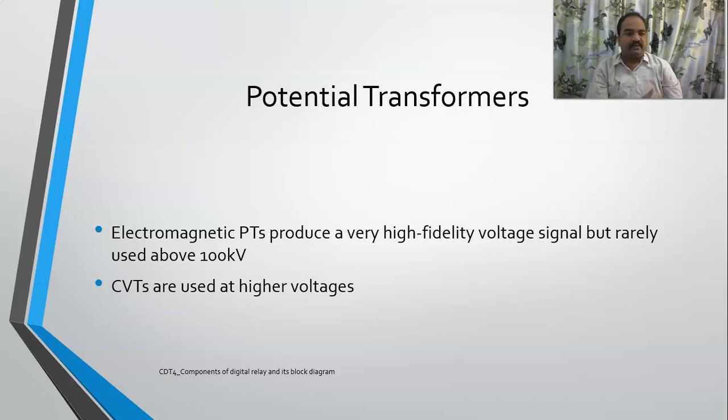One is the conventional electromagnetic potential transformer, and CVT, capacitive voltage transformers, we do employ, and the latest one is coupling capacitor voltage transformers. They are sometimes called CPT also, capacitive potential transformers.